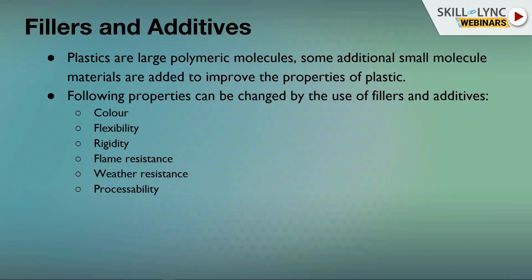For example, the material which we went through previously will be mixed with some other materials. Like, if you look at a plastic material or a physical part, and observe it on the B side, you see the plastic material written on it, like PC plus ABS or PA6 plus GF15. So it's mixed with glass fiber 15 or glass fiber 30 to increase the stiffness or its mechanical properties. And that's the reason fillers and additives come into play.